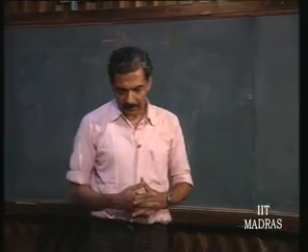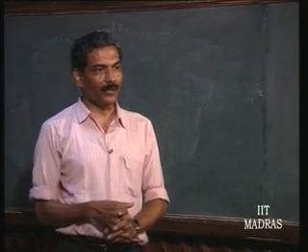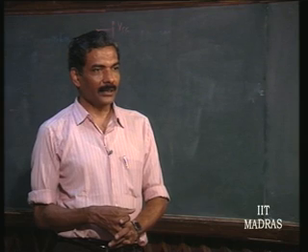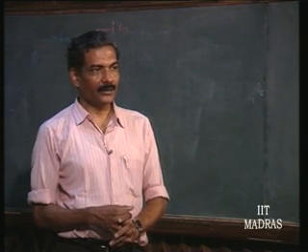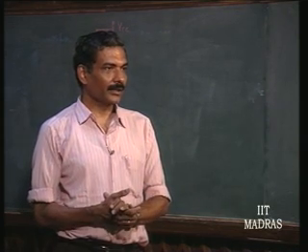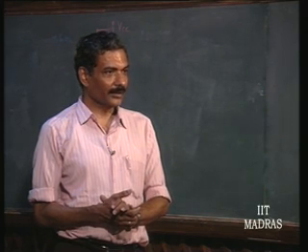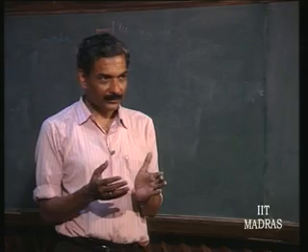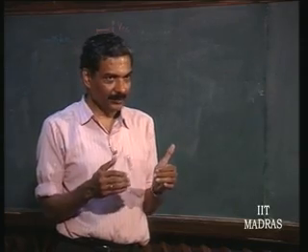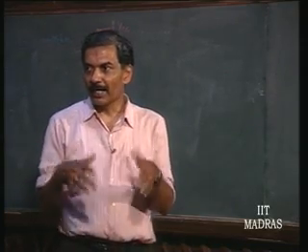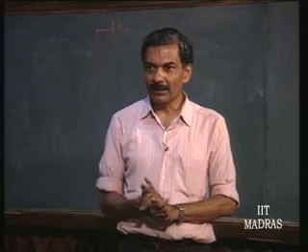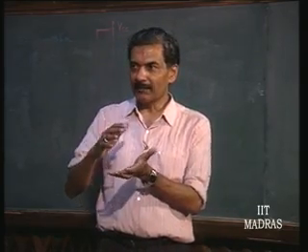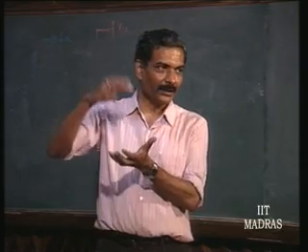The other amplifier which we have already touched upon makes use of the principle that we had enunciated in the introductory lecture on the translinear principle. That is, you can take a differential input current as the input and keep on amplifying it by using what is called Gilbert's gain cell. And these cells can be put one over the other.